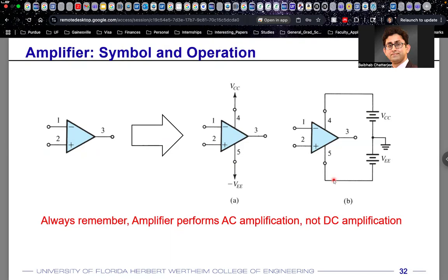You did not have an op-amp in this circuit. Still we talked about the concept of gain, because the concept of gain is universal. Gain just means output divided by input. Whatever quantity you have at your output, divided by whatever quantity you have at your input. So that's just a universal definition of gain. If you had an amplifier somewhere in between, let's say I include an amplifier over here with a gain of A or a gain of 5, then things will be different.